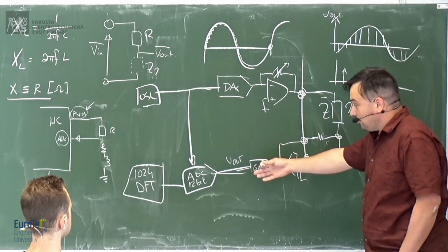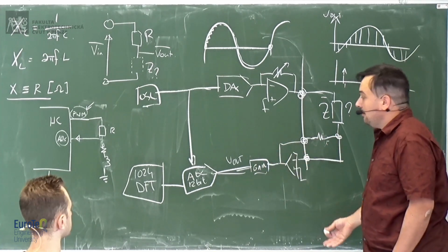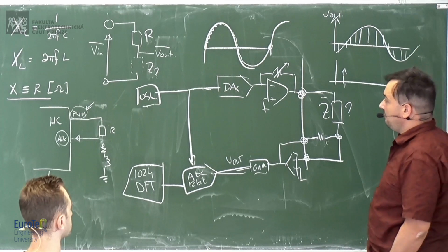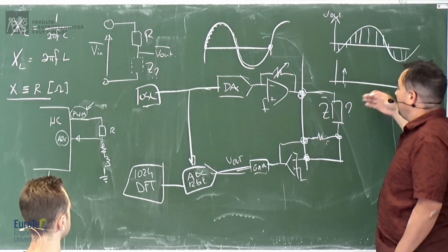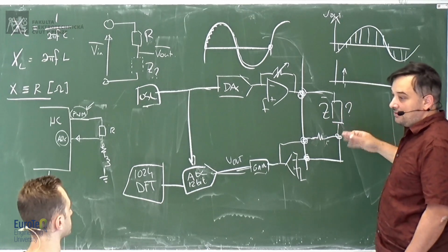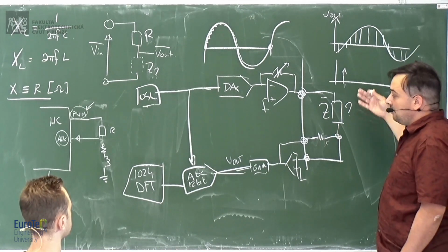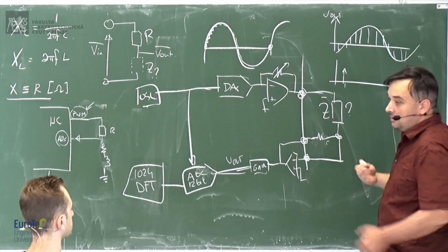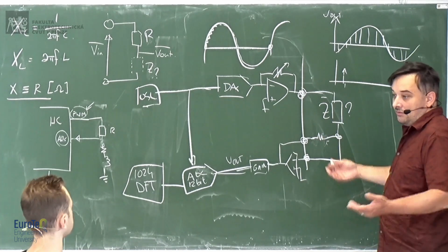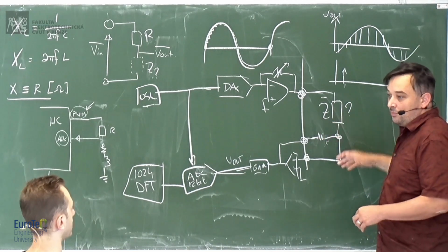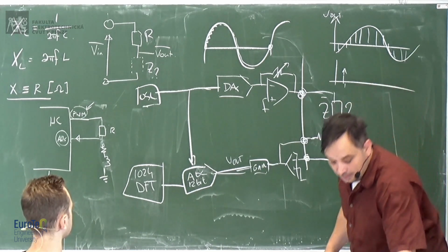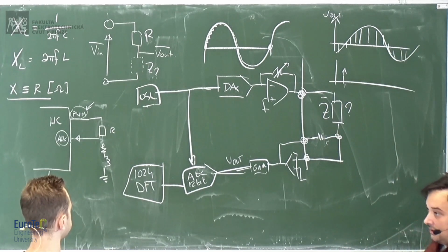So, of course, you can do it also this way, digitally. If your system is precise enough, synchronized well enough, then you don't need to make any flip and so on. You just calculate the digital Fourier transform and there you have it: digitally you have done the same thing that otherwise you would do by multiplying and so on. All on a chip. Exactly.